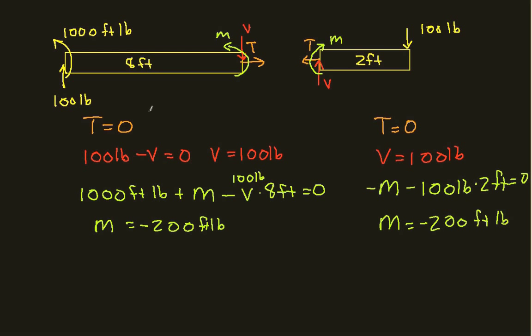So what we've shown here is how to find these forces, and it also turns out that it doesn't matter which free body diagram you use after you've made your cut. You'll get the same answer if you use the one on the left of the cut as you will get when you use the one on the right of the cut.